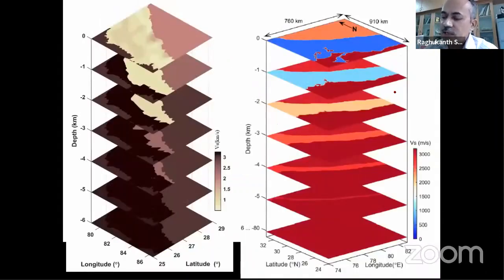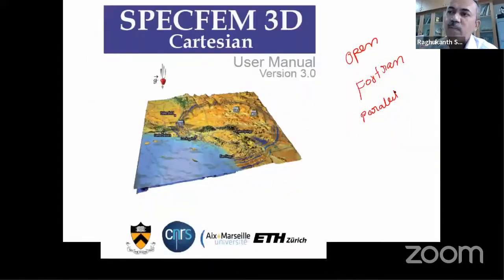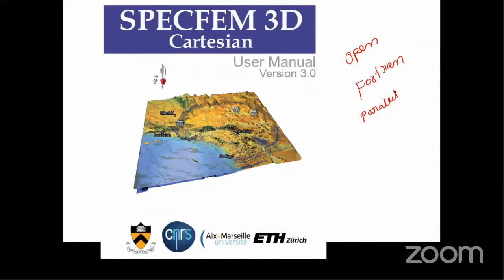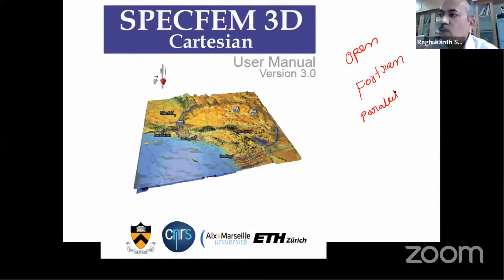So what we have done is we have already implemented this code. It took a lot of time on our supercomputers, and then we have written some subroutines also to process the data, and to define the finite faults and other things. So there are some subroutines we also developed, but the main code comes from SPECFEM3D Cartesian. So now we use this spectral element method to simulate ground motion in our Indo-Gangetic Basin also.